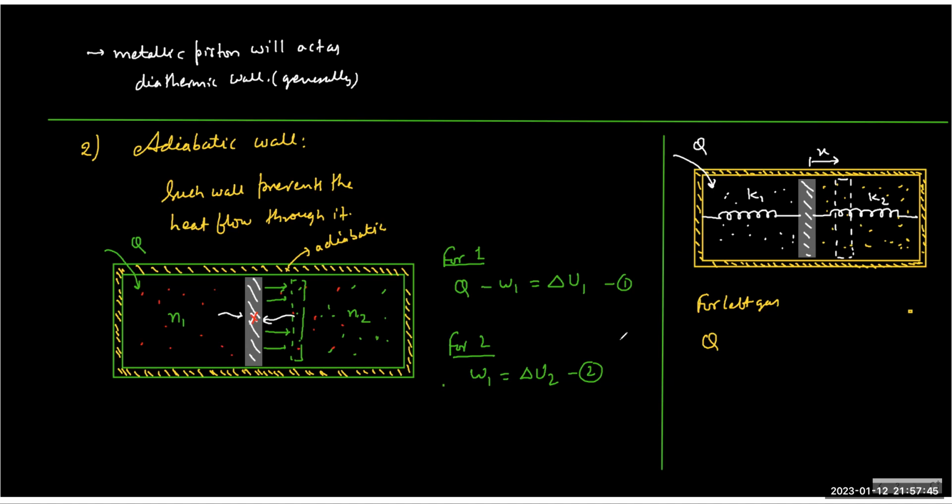Now, here it is interesting. It's difficult to write the work done by the gas, because the gas is giving energy to the piston. The piston is, of course, giving energy to the two springs and also compressing the gas. So there are three types of work. The third is unknown. But if I take the entire thing as one system, then we can say something. Out of the energy given, Q, how much energy is stored by the springs?